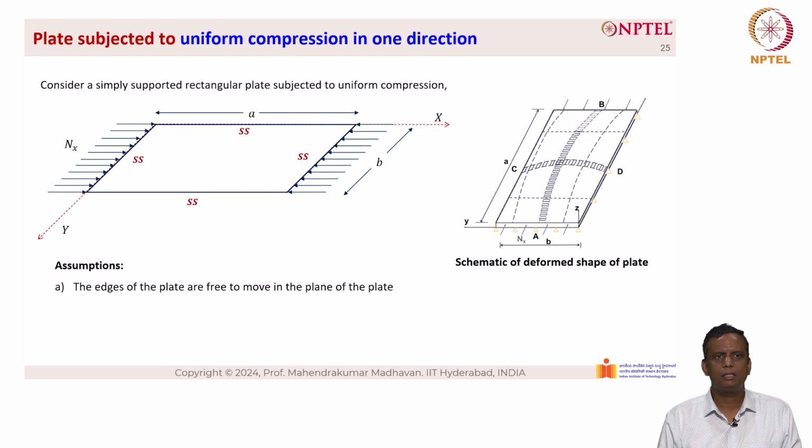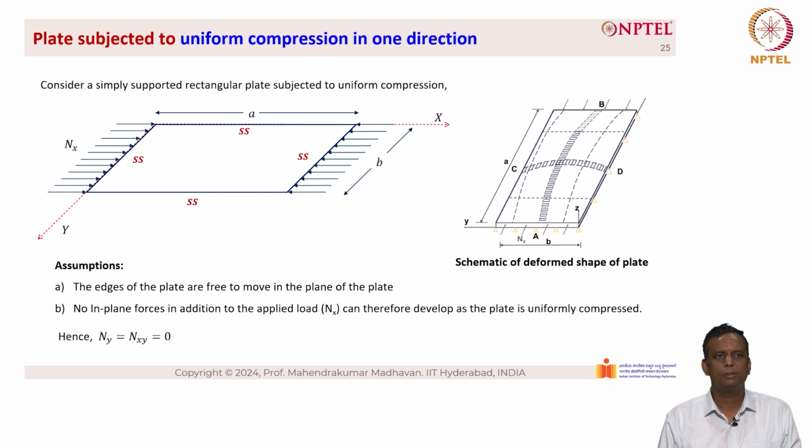The assumptions are: the edges of the plate are free to move in the plane of the plate. No in-plane forces in addition to the applied load Nx can therefore develop as the plate is uniformly compressed. Hence, Ny equals Nxy equals 0.